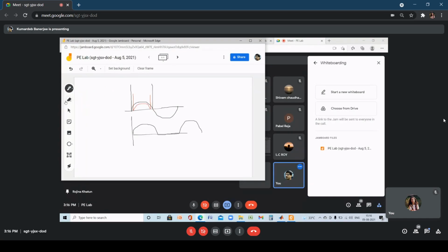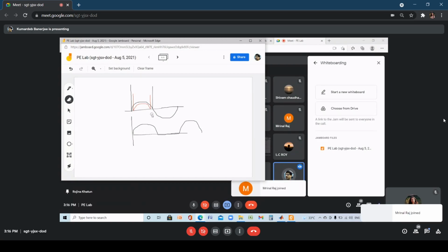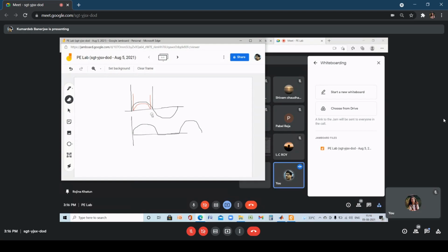Okay, so if you think of these two vertical lines, then a time span between the two vertical lines is 10 milliseconds. Okay, but the time span between these two red vertical lines is definitely less than 10 milliseconds. And this is happening because the diode is not conducting until unless the voltage goes beyond V gamma. So it's very important because it totally changes the power equation or power that's being delivered to the load.